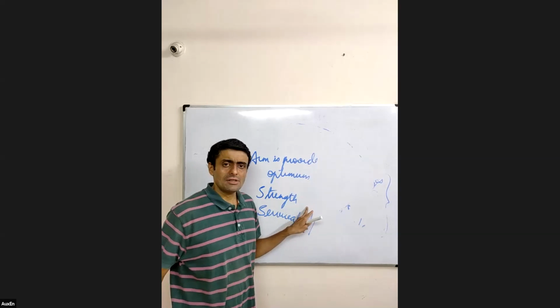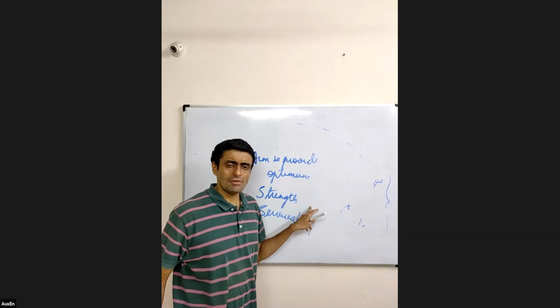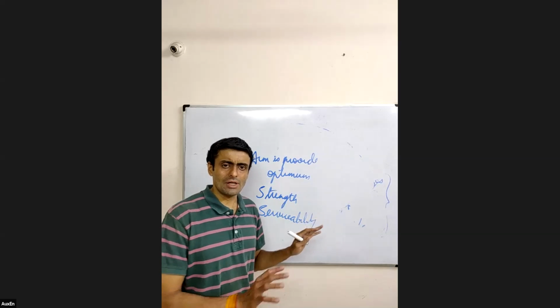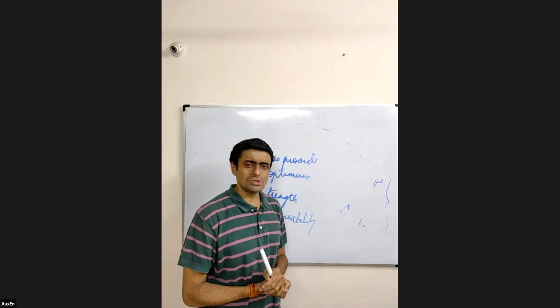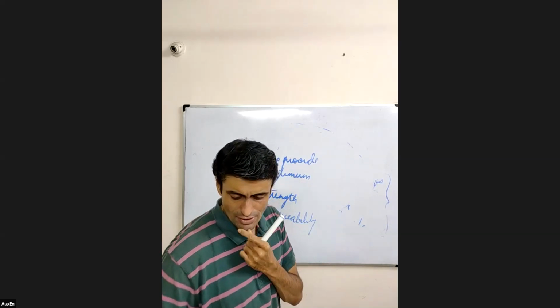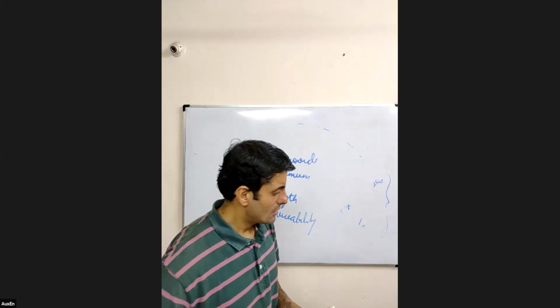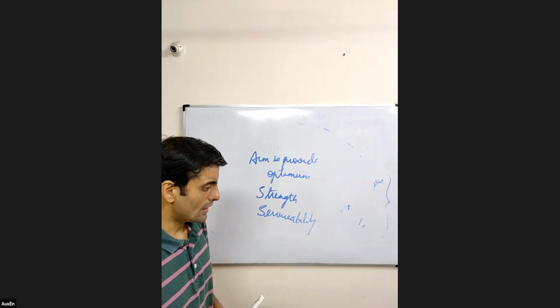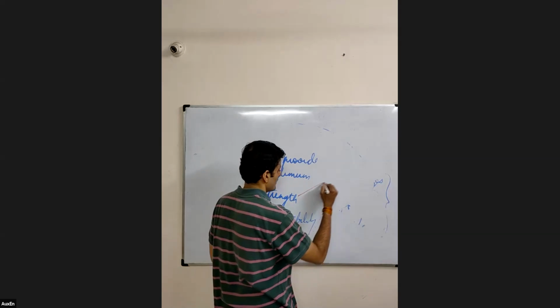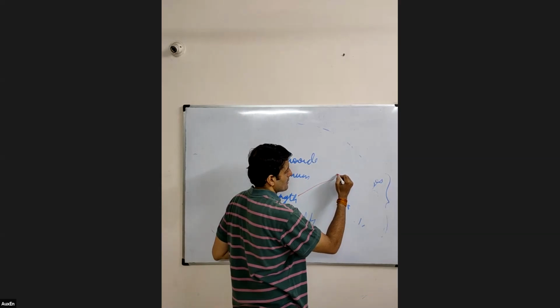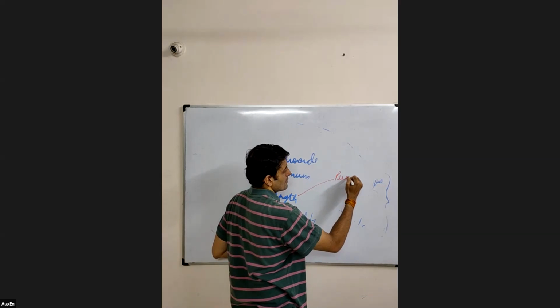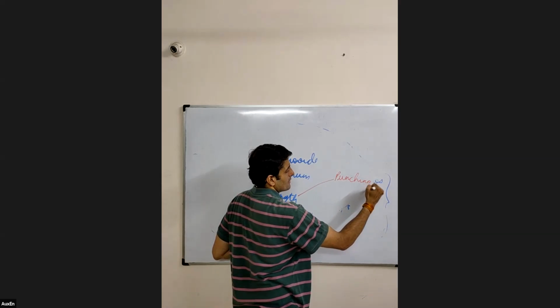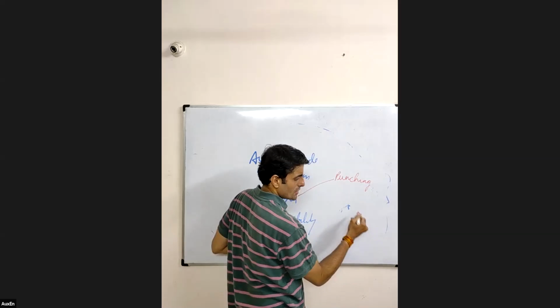So in strength, what are the issues that you would be checking with respect to a flat slab system? Right now I am talking about what are the issues that I would be checking with respect to the strength criteria. So I would be checking, I will say, for strength, I will check punching. This is my major headache. I will check punching shear.